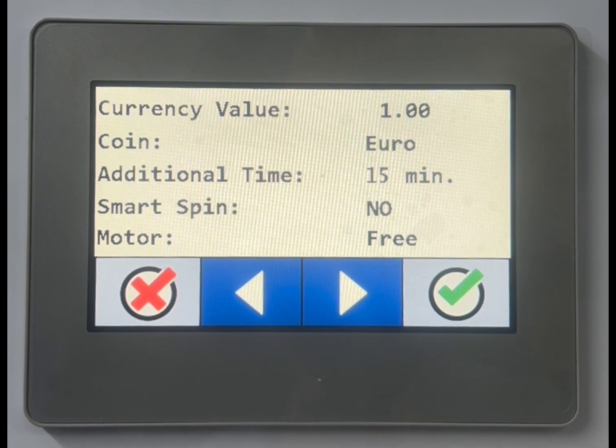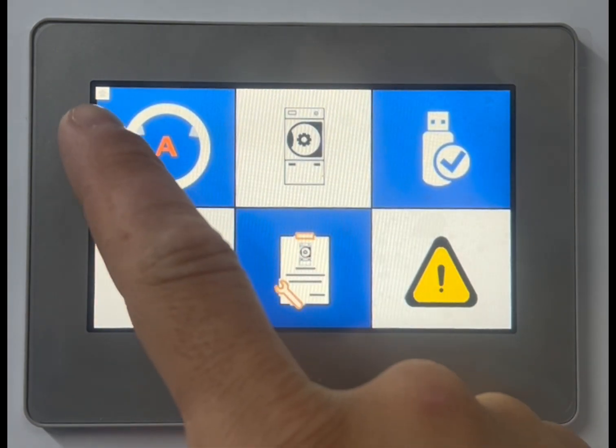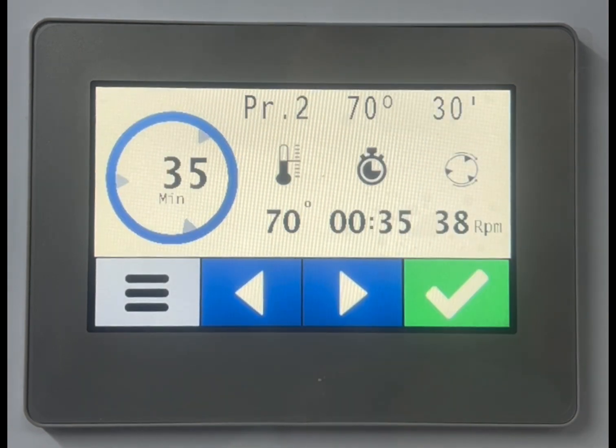And we have, last but not least, the type of motor. You can have the freewheel motor or you can have the lock motor. So it's important if you install a new motor to check the value of this parameter, because the configuration in the inverter is different. Again, if everything is ready, you can press OK. It will save the parameters, and after that we go straight to the automatic mode to run the machine.